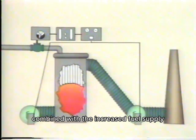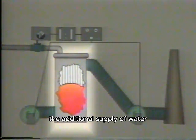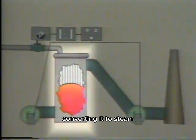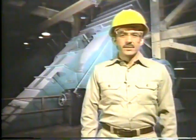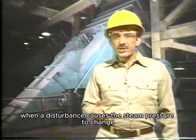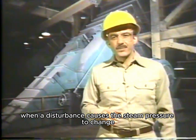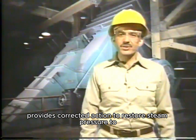Combined with the increased fuel supply, combustion in the furnace is able to heat the additional supply of water, converting it to steam and restoring steam pressure to the desired level. This control loop is a feedback control loop because when a disturbance causes the steam pressure to change, the control loop provides corrective action to restore steam pressure to the desired value.